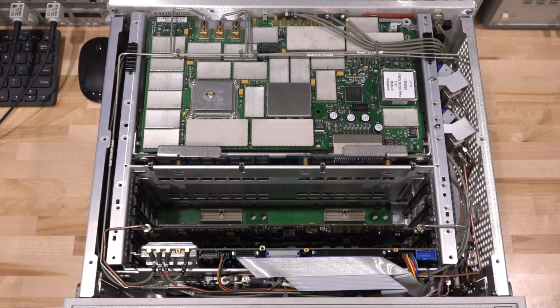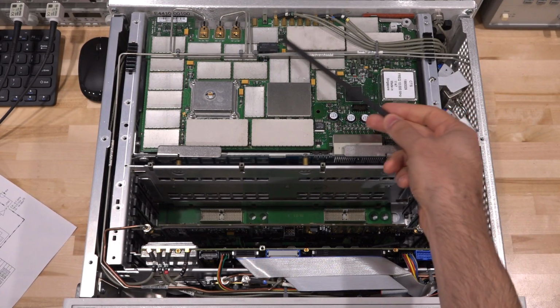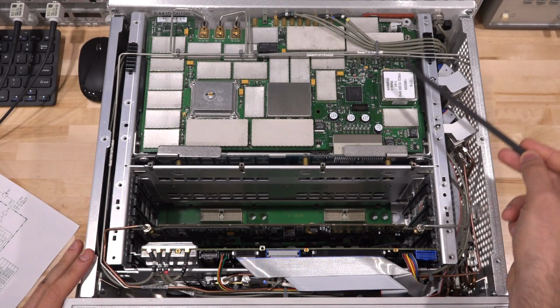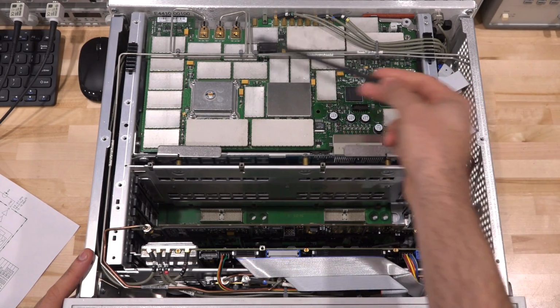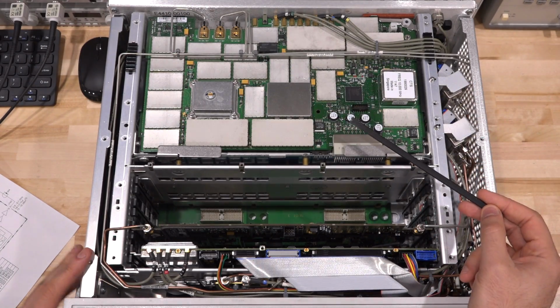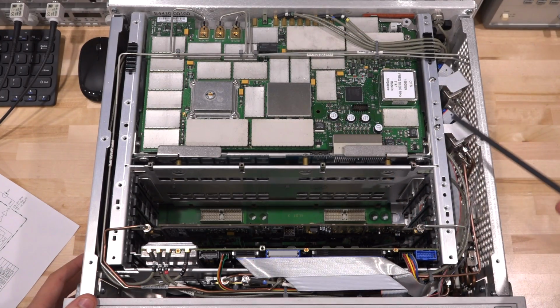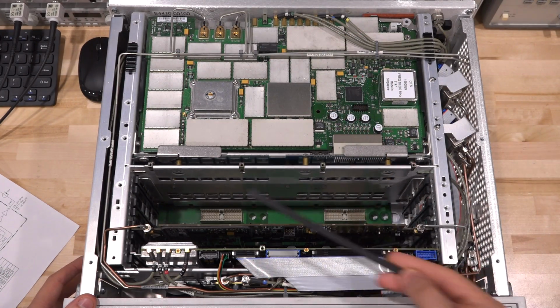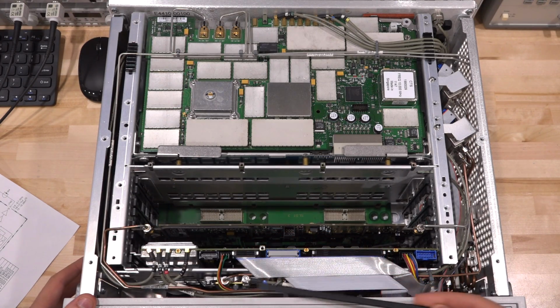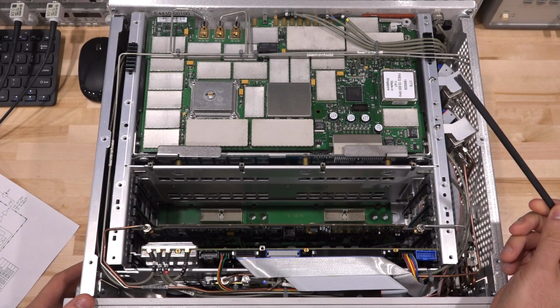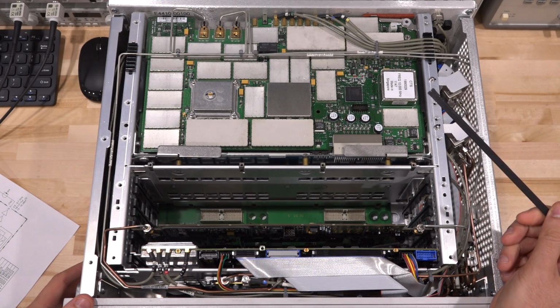And just to remind you, the board that we're interested in testing, first let me actually talk a little bit about this one. So this is the synthesizer board. This is where the 10 megahertz crystal is, this is where the DRO is, and all the different filters and multiplications and PLLs are on there. The output of this is what goes around over here and is fed into this board, and the output of this board is the first LO, which then goes into the first mixer there. Now, by the way, the clicking noise you're hearing is the MXA booting up and doing self-alignment.